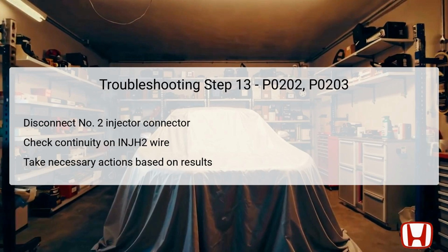For this check, you must disconnect the number 2 injector 2P connector to facilitate testing of the INJH2 wire. Conduct a continuity assessment to verify the wiring integrity between the injector and the PCM pin.